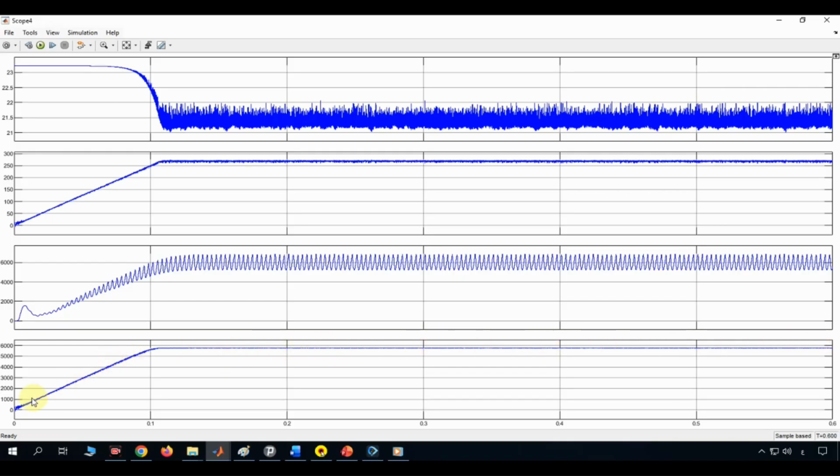Putting those two observations together, this looks like a reference or filtered version of the power trace right above it, the target power level the system is aiming for, or a smoothed average with the switching ripple removed. It settles at a slightly higher value than the average of the noisy power trace above it, which is consistent with it representing a clean set point rather than the actual ripple-affected measurement.